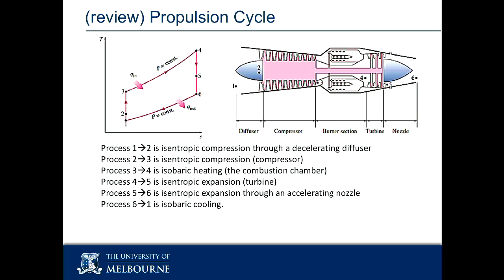When we've done nozzles and diffusers so far, in the tutorials and in the lectures, their job is to change the velocity of the fluid. And so what you're doing is converting enthalpy into kinetic energy or kinetic energy into enthalpy. There's no heat transfer and no work done. So you've got Q minus W equals delta H plus delta KE. That's the important bit. This is one of those ones where you can't just cross off the delta KE, the change in kinetic energy. So we'll play with those in the worked example. We'll have a worked example of a gas turbine and a worked example of a propulsion gas turbine. So we'll do one of those diffuser examples.